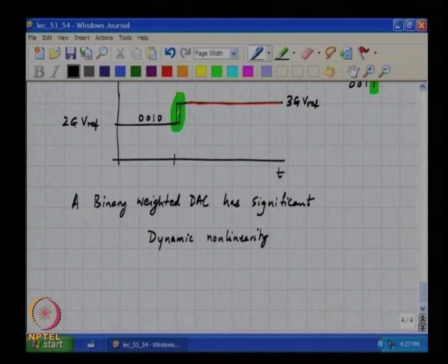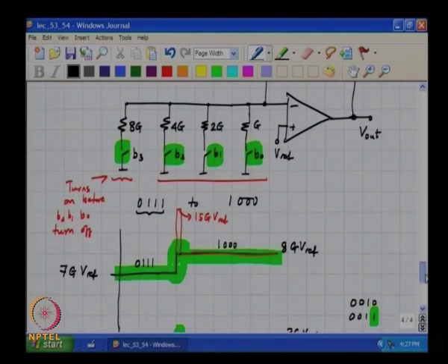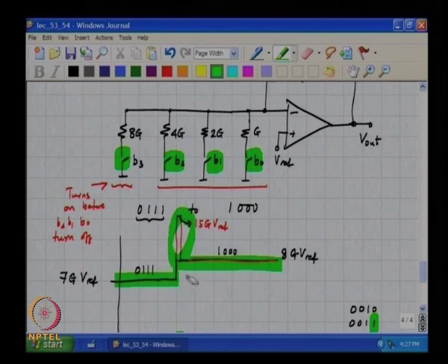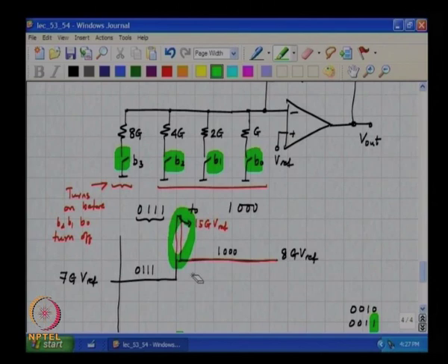the fact that a binary weighted DAC can be terribly nonlinear, especially when these glitches become, I mean clearly if this glitch is infinitely thin, then presumably it causes no effect on the output waveform, but as this glitch becomes a bigger and bigger portion of the switching period, this becomes an issue. Is this clear?